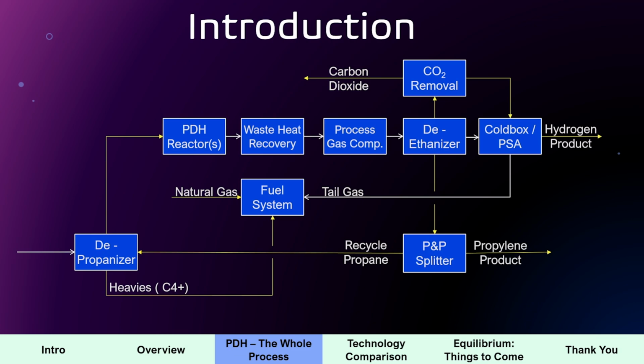Mm-hmm. Yeah. So unlike in a typical ammonia plant or fertilizer plant, where you need to purify CO2 because it's an oxidizing agent and you need to get rid of it before going to the converter, here it doesn't have any purpose beyond needing to be separated. Otherwise it's going to cause physical damage on your cryogenic surfaces.